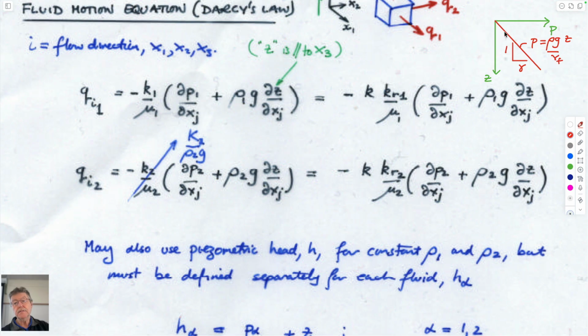But we know that this gradient, which is not 0, is sitting in a static fluid. It doesn't make any difference if we filled that swimming pool up with porous media, it would still not be flowing. So the velocity of this fluid should be 0. That's certainly not honored if we only have this pressure gradient, which in this case would be in the z direction. This would be finite, it'd be non-zero. So it would suggest that since these coefficients are also non-zero, there'd be some flow rate in this particular direction. That's not the case.